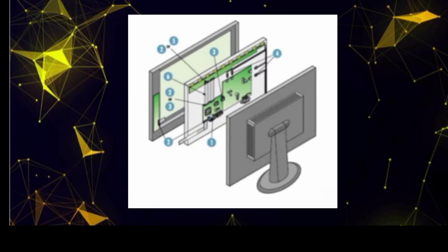Interface-related parts include the D-SUB socket, D-SUB cable, DVI socket, DVI cable, and DisplayPort cable. These handle video signal transmission between the monitor and external devices. Internal connections. FFC are flexible flat cables, FPC flexible printed circuit connectors plus data cable used for internal data transfer within the monitor between the main board and screen panel.